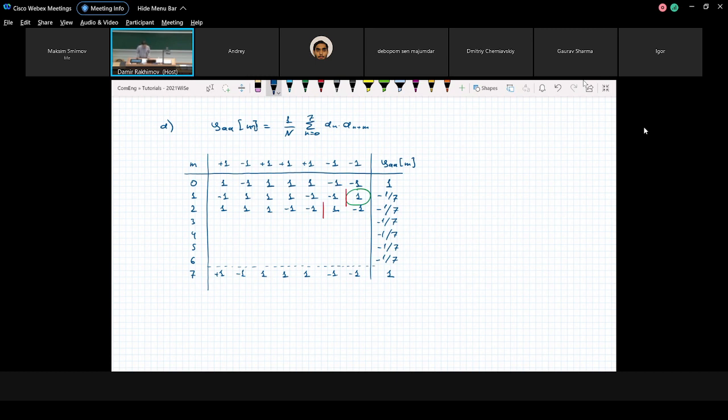Now, first of all, you already see the difference, because for an energy signal the autocorrelation had a maximum value and then went to 0. If the difference between indices is big enough, the resulting correlation will be equal to 0. But for a periodic signal, the autocorrelation function will be periodic.